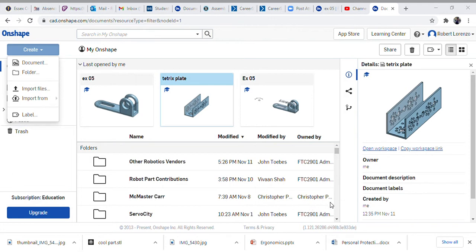All right, and then we see some other simple measurements. We see this is 40, right? From the top edge to the middle is 40. But again, we look here, we see this is a 25 radius arc. So if it was 40 from the top edge to here, we have to go another 25. So this will be 65 tall when we get there. All right, so this line here is going to be 65 millimeters. So with that basic knowledge, let's get started drawing.